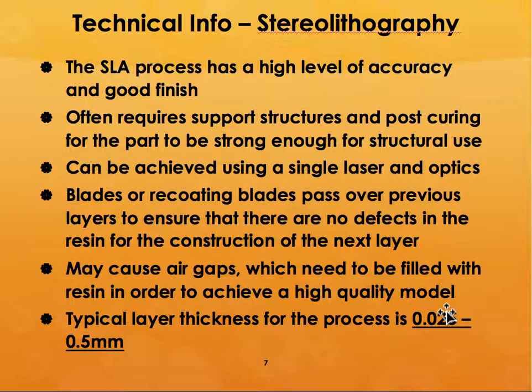What is the technical information that you can get from this process? The SLA process has a very high level of accuracy and extremely good finish. In the beginning, the layer thicknesses used to be of the order of half a millimeter at the most, but now you don't need that much. You can probably have a couple of 100 microns or maybe even 50 microns. So by building it layer by layer under such small numbers, you can get extremely small and accurate